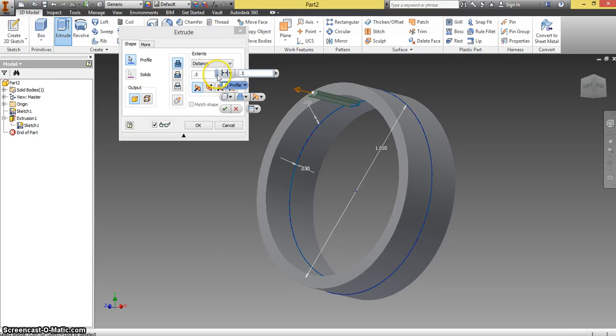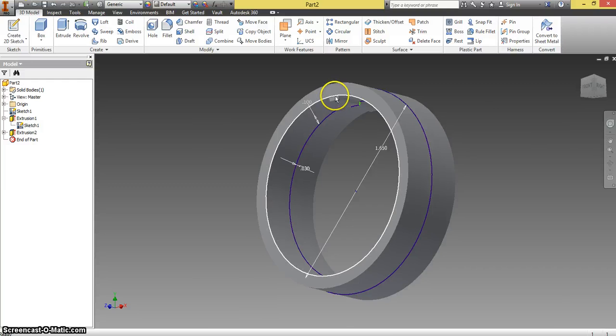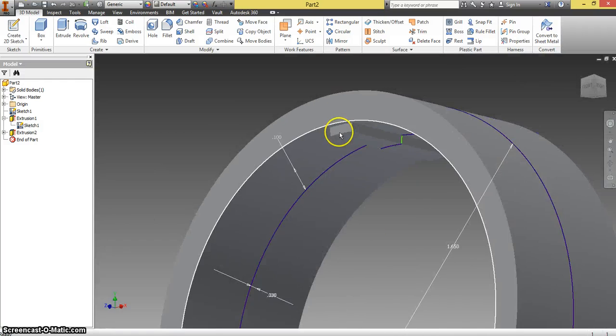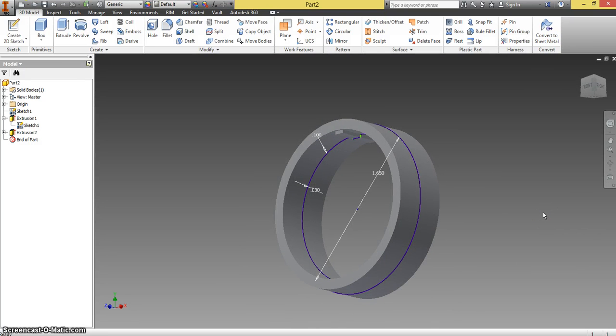And actually I told you guys I'd rather use this thing here. Put your distance in here, and then I need a midline extrusion of this thing as well. 1/2 inch midline, that looks good. Going to hit OK, and you can see why we wanted a midline extrusion, because we want a little space on either side, this little space right here. So I like that.